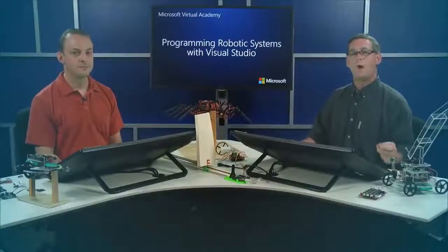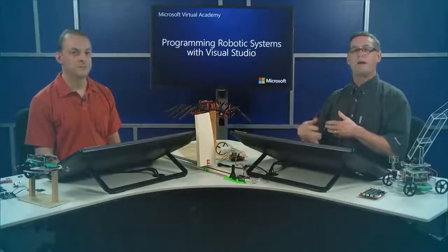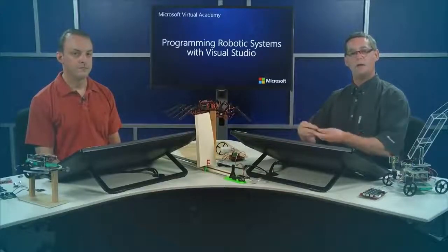Paul, with the wiring, a lot of times I'll leave my wires a little bit long, and then I'll be able to cut them and resolder if I have to. Leaving it a little bit long gives me that leeway to see where I want to route it in the end. I'm not saying I leave it a foot long and it's all coiled up somewhere, but leaving a little bit of slack in case you need to move it into a different position sometimes is good. So I will do that, but I do try to think about how I'm going to have it laid out and get it close to right the first time if I can.